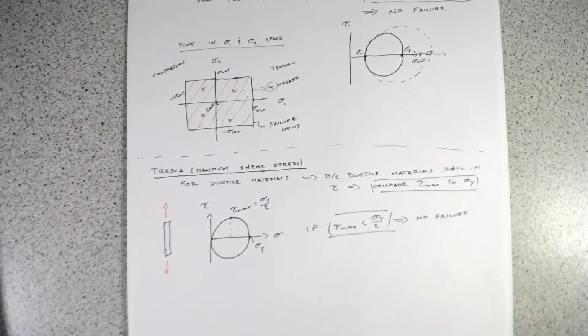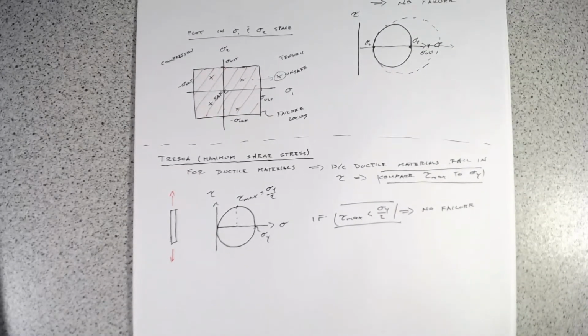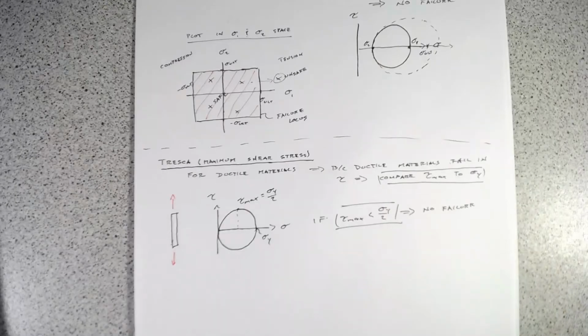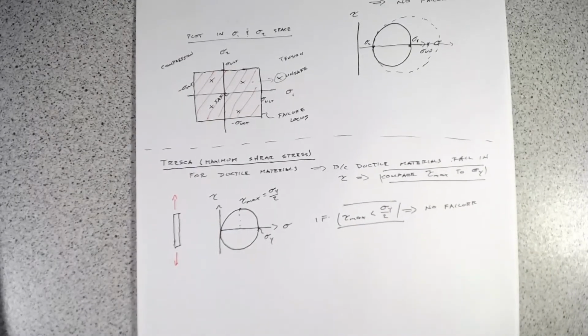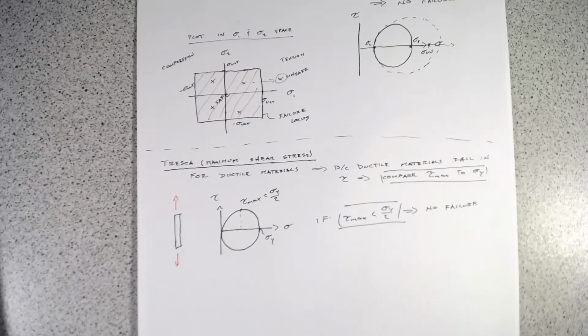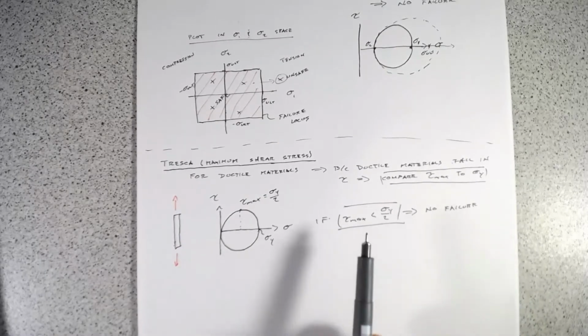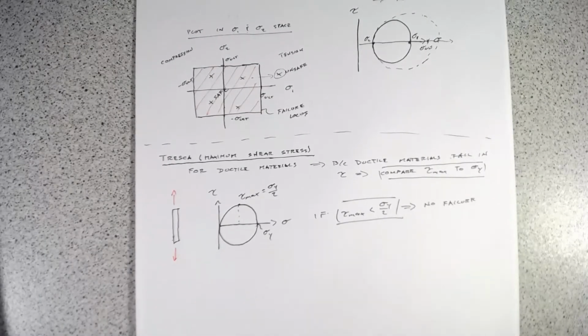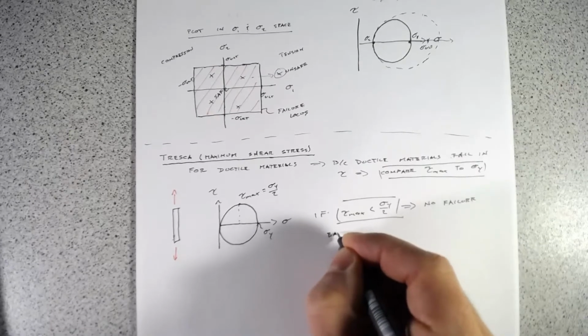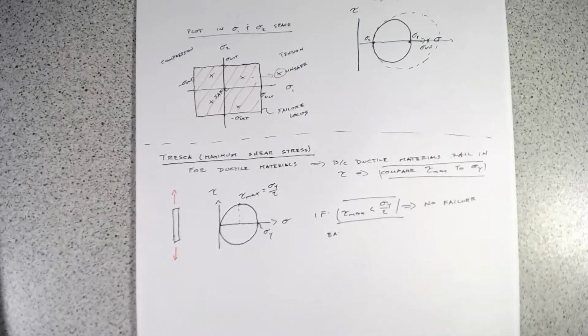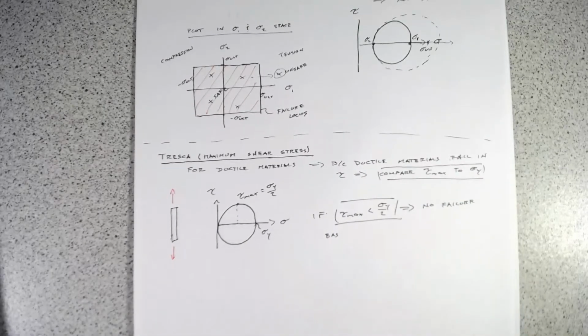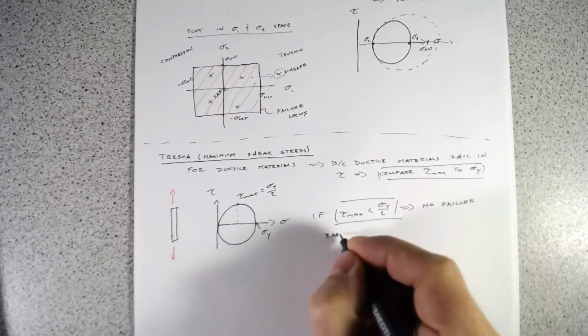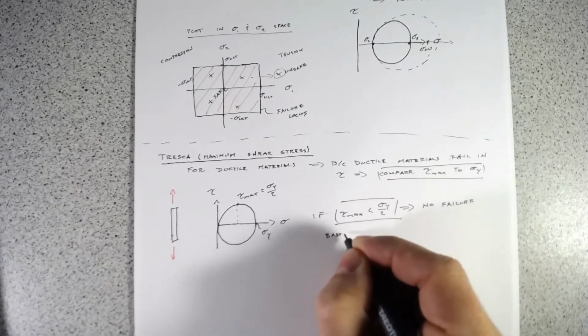And again, it's a fairly straightforward criterion. So how do we use that in practice? Well, either we can build a Mohr circle, or often finding principal axes tends to be a bit quicker and easier. It's more convenient to compare normal stresses to normal stresses instead of shear stresses to a normal stress. So basically what we're going to do is compare diameters of Mohr circle as a proxy, and that it's equivalent, but it's more analytically convenient.